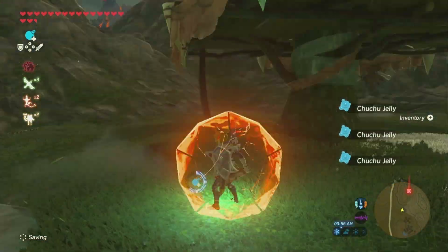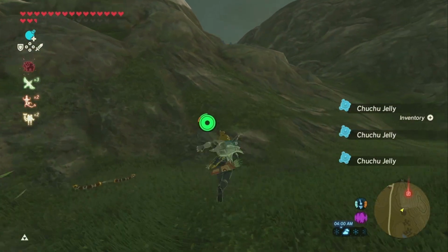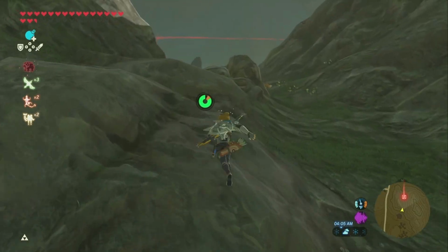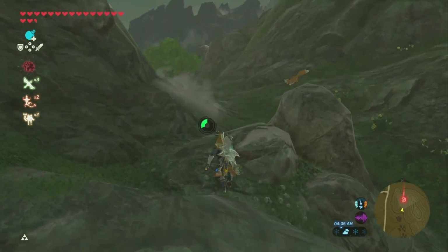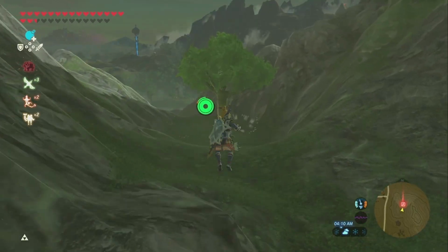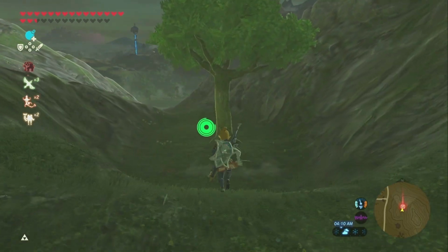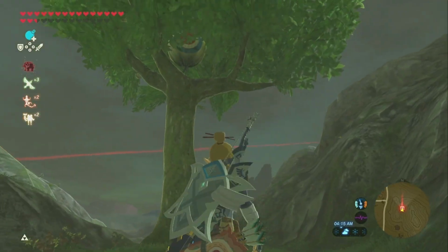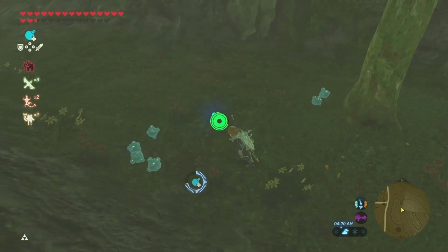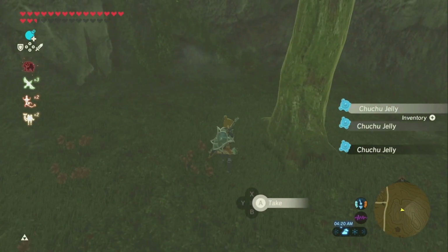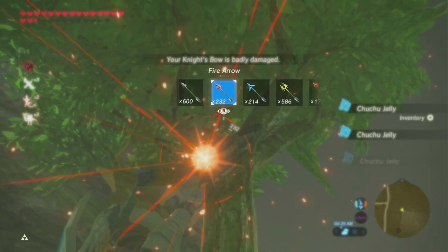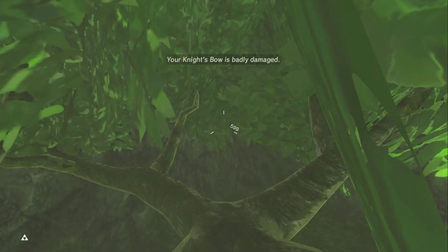Gas or oil-fired water heaters should not be located in sleeping areas, including bedrooms or bedroom closets. We also don't want gas or oil-fired water heaters in closed closets or bathrooms. We're worried about backdrafting appliances killing people in their sleep and about inadequate combustible clearances. Some areas allow direct vent water heaters in these areas because the chance of backdrafting is very small.